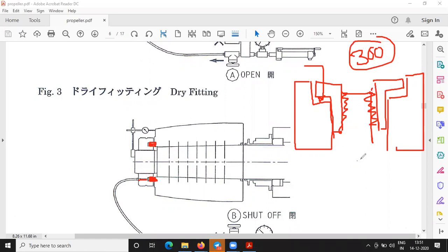But if the elongation is not met completely, the oil still has some space to go and occupy. As long as we keep giving strokes, it will still show us 0. Yes or no? Yes, sir. Once the stud starts getting elongation, at that time there will be an increase in the pressure, because it is the pressure that has to overcome the strength of the stud to elongate it.